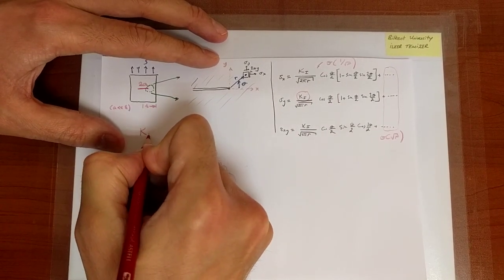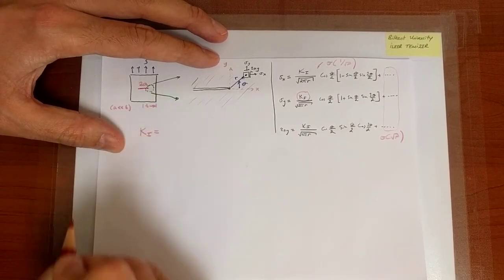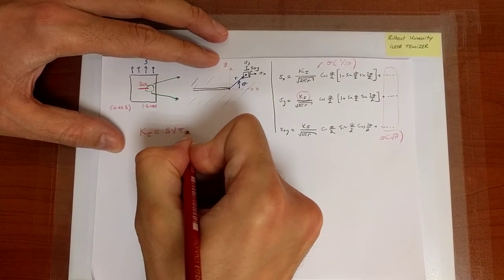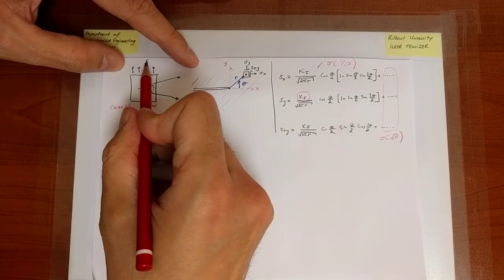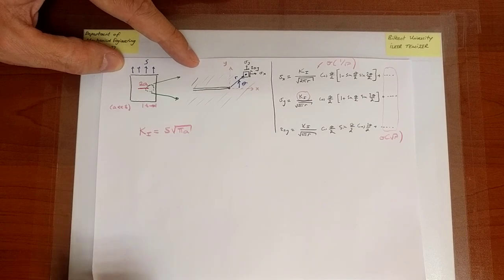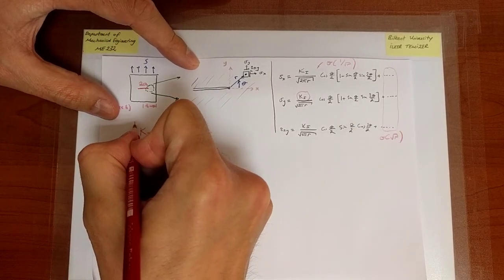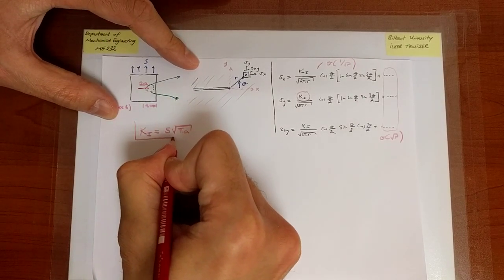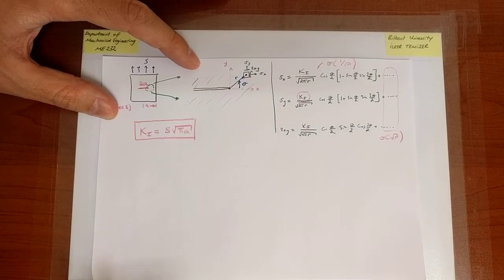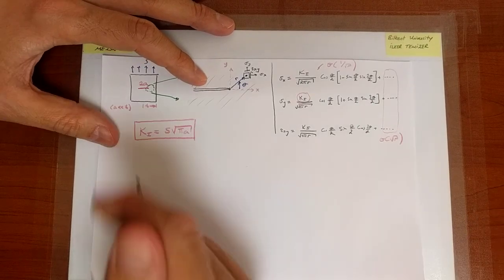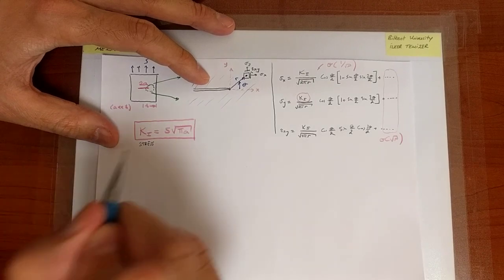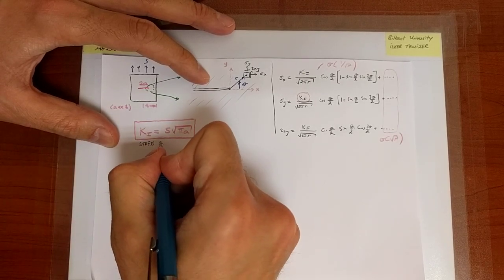That factor is something known, and it is simply equal to S root pi A. S is the far field normal stress, and A is the half width of the crack, square root pi. Now, immediately embed this expression in your minds because it's something we have to know by heart. This quantity is called the stress, not concentration factor, but intensity factor.